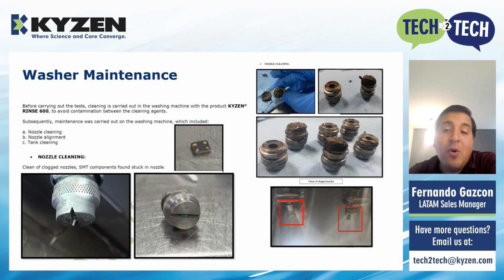When most of our nozzles are blocked, we can have sections of the conveyor belt that are not being covered or reached by the streams. We are limiting the capacity of the washer to perform its job of removing the desired residues. As you can see in the picture on the bottom right, some spray streams were deviating due to this obstruction and not hitting the boards as required.